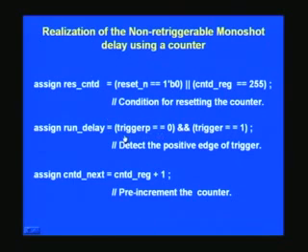What you can do is you can have another signal which will store the previous value. So every time the clock strikes, you can push the current value into another flip-flop and store it and use that one in the next clock. So you will know what was available in the previous clock, that status here. So by ANDing this, say for example previous value is 0 and present value is 1, naturally you can sense that it has a rising edge as far as this signal is concerned.